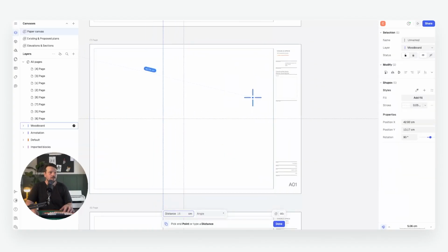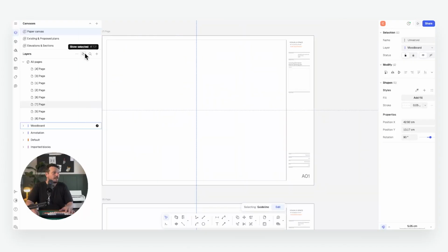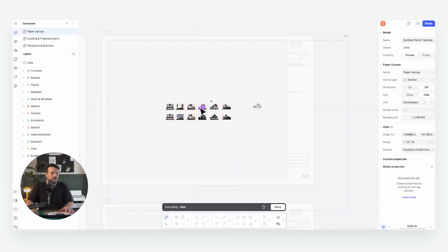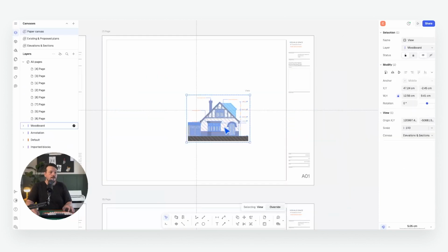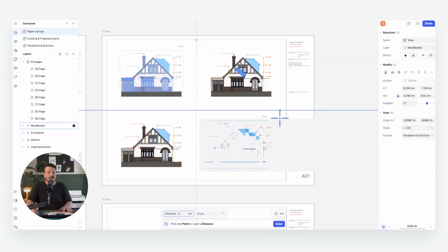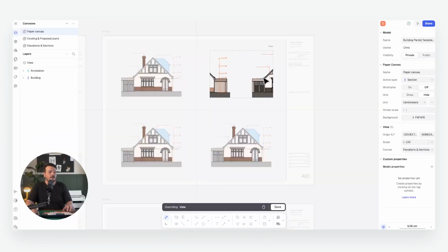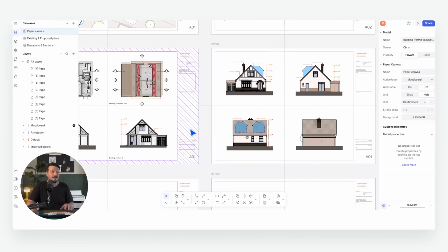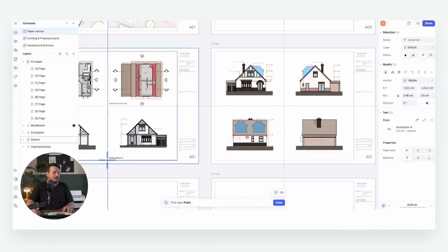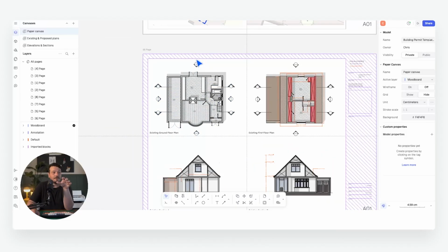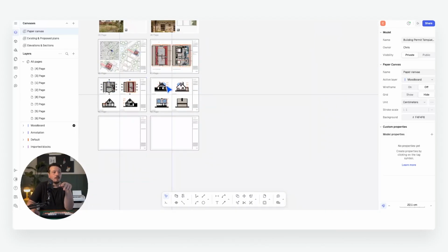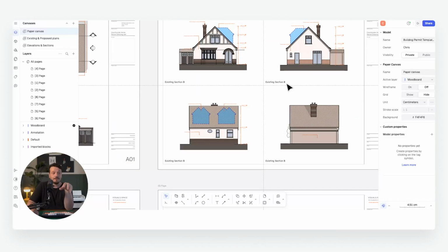And I'm just going to show you with the elevations very quickly. You just do exactly the same process of new view, elevations and sections. You obviously find the existing, set the scale, crop, position across, and then you just change obviously the thing that you're looking at in the crop. But again, that's how you set up those elevations, and we can very quickly copy across those notes, and we can obviously reference the elevation tag, so 1, 2, 3, 4, with the titles of those elevations.